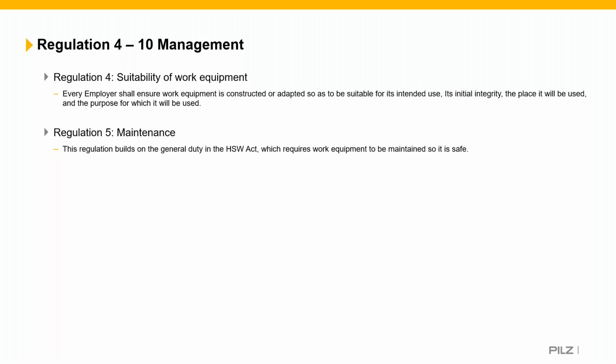For safety-critical parts where failures could lead to immediate or hidden potential risks, formal systems are needed based on planned preventative maintenance, so replacing parts or making adjustments at set intervals to avoid risks, deterioration or failure of equipment. Also condition-based maintenance, so monitoring the condition of it to ensure that it's still suitable to carry out its intended use.